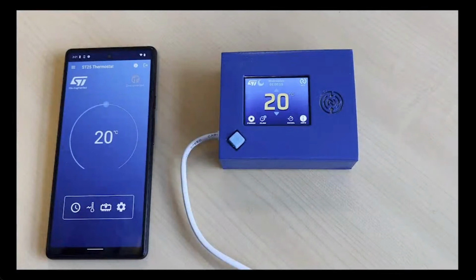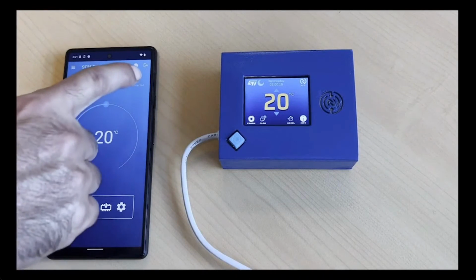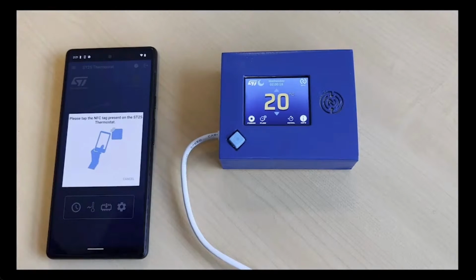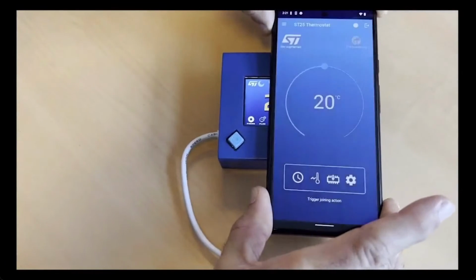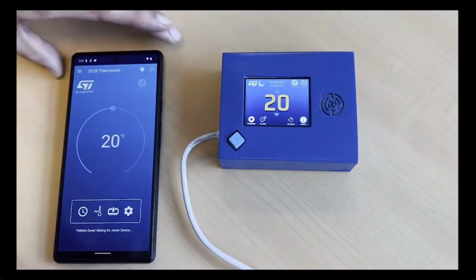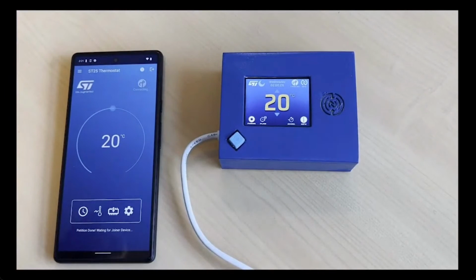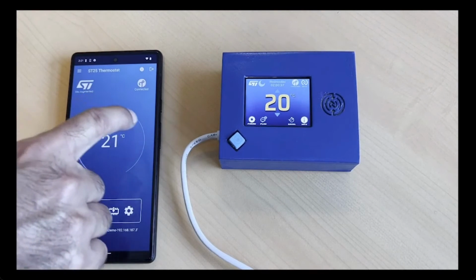To start the commissioning, we click on the Thread logo on the mobile app of the smartphone and then tap the joiner device to get its unique ID and password. We can see the logo blinking during the connection. On the smartphone, we can see the sequence of steps of the process. Once the process of commissioning is finished, the logo shows the device connected and both logos stop blinking. The device is commissioned in a single tap.